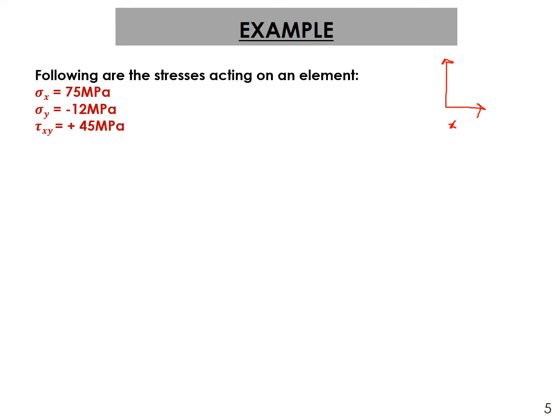There are two conditions. If you are moving along the positive x-axis, as I'm showing here, and you get a face here, say this is a face, I'm not drawing the whole diagram, and on the face you get a positive shear in the y direction, then both are positive, so it becomes positive. That's how we mark positive shear stress.